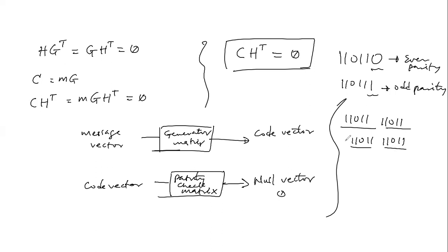So these are different blocks. This is repetition code. So what if I now receive 11011, 10011, 11011, 11011? I can tell based on what I have received that what was transmitted is 11011. So that's another way of making corrections.